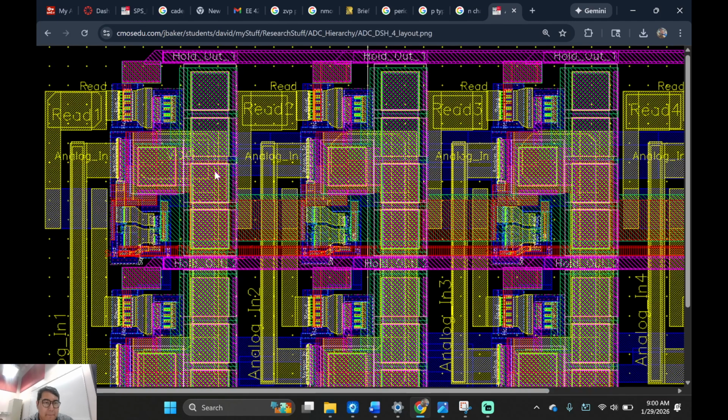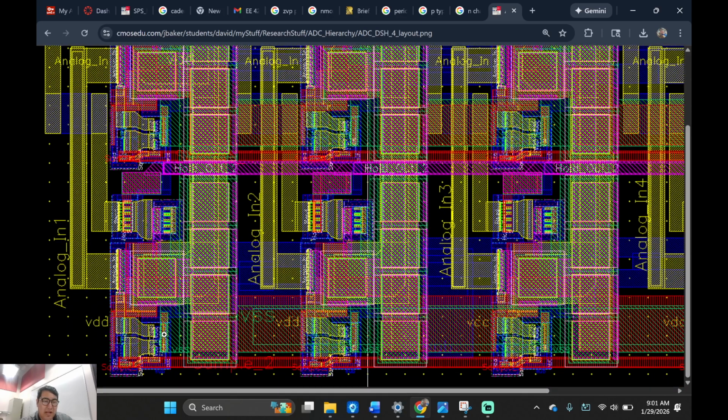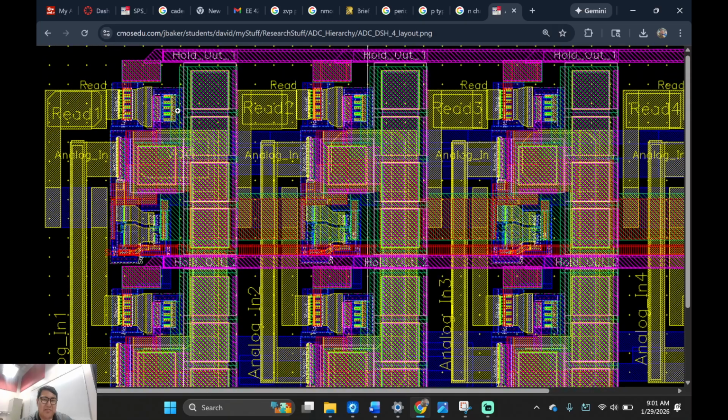Let me show you this picture. This is my second layout once I started practicing Cadence a lot. You start having more professional things. You can start seeing there's more organization. You see these right here. These are called our power rails, right? Signal rails, power rails. Apparently, the way the industry works is you have to create a frame so that your piece fits. Let's say someone says, we're all creating a project, make it 100 microns tall, and that's pretty much it, because we're just going to create it like Lego pieces, okay?